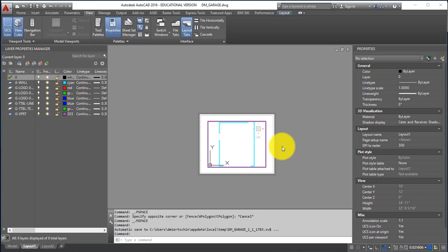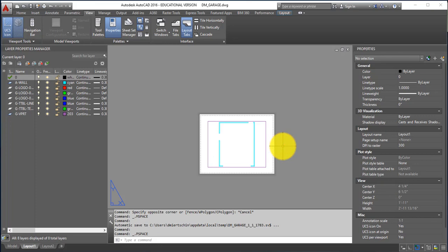So now it's time to insert the title block and merge it with this drawing. I'm going to go ahead and exit the viewport. This is important because if I put the title block in when I'm still inside the viewport, it's going to remain 11 inches tall in model space. I want to insert it in the Layout tab. So double click, and now I've exited the viewport again.